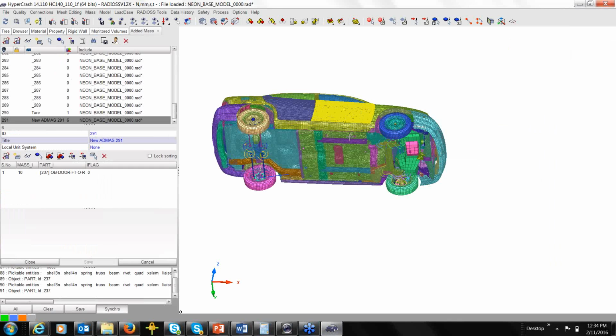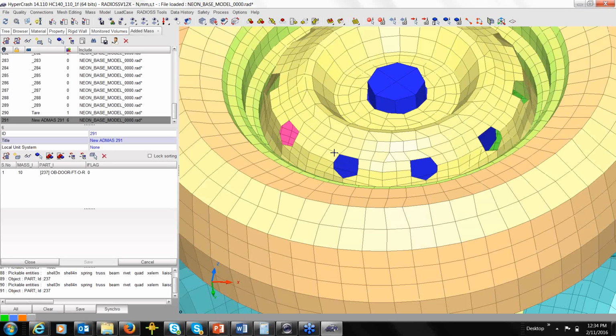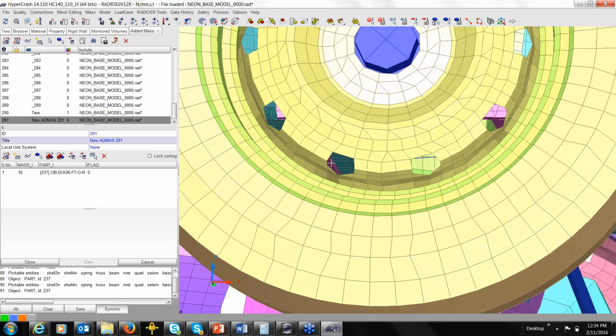Beautiful. You see on your FEA, you do an approximation, and element size depends on the geometry. Sometimes you have a very complex geometry where you have a hole, and you need to model those holes. If I give you an example here, let's say in this tire you have some holes here.